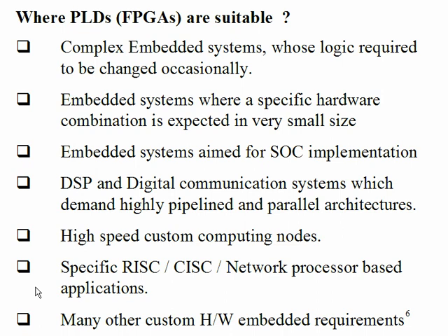In the case of RISC, since each instruction takes relatively only 2 or 3 clock cycles, it is almost similar; almost all instructions take the same amount of time. So it is easy for the designer to improve the performance, the speed, by implementing a concept called pipelining.